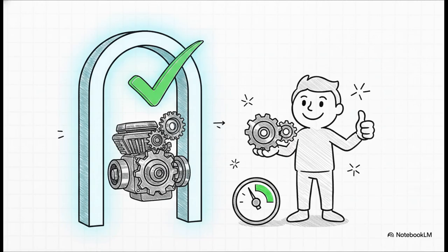Then we arrive at phase 4, product and process validation. Look, this is the ultimate test. It's showtime. The manufacturer conducts a significant production run under actual, real-world conditions. During this run, the team confirms that the control plans and operator instructions are actually working the way they're supposed to. We get our measurement system analysis, or MSA, results back, just to ensure the very rulers and sensors we use to check quality are actually accurate. And ultimately, the customer validates that both the product and the manufacturing process perform exactly as intended.